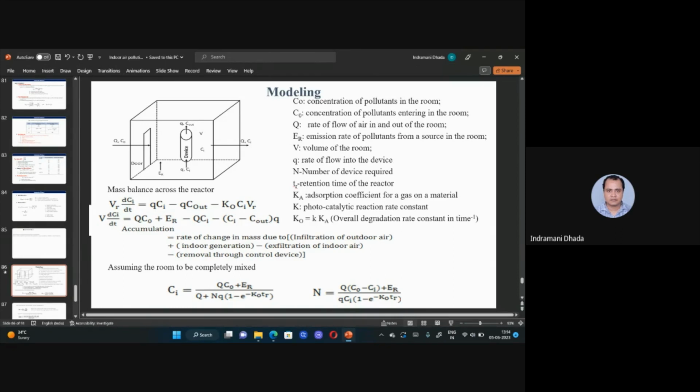You know the concentration which is released at the source. Then through the modeling process you can define the concentration which can reach the receptor at a distance in x, y and z coordinates. You can say that the concentration at this particular point will be this much. Now, you know the concentration of that particular pollutant permitted per man is this much. Suppose the concentration of SOx is 40 ppm per man, and you see through your modeling that the men sitting at that certain place are being exposed to 60 ppm. So you have to reduce 20 ppm.